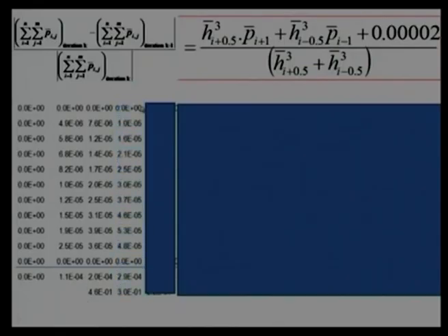We continue. In iteration number 3, as I mentioned, the first node and last node will be at 0 value. These are the boundary conditions, we are not varying them, and the remaining terms are increasing. Instead of 7.6, the pressure at node number 2 has now reached 1.0 × 10^-5, and these are all non-dimensional numbers. It is slowly increasing, and we can see the same trend: the maximum pressure occurs at node number 9 instead of node number 10.